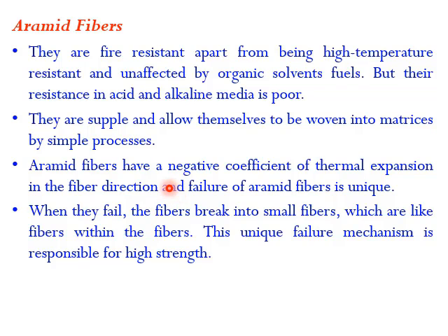Aramid fibers have a negative coefficient of thermal expansion in the fiber direction, and the failure of aramid fibers is unique. One has to understand this failure to understand the behavior of these materials in a practical application. When they fail, the fibers break into small fibers, like fibers within the fibers.